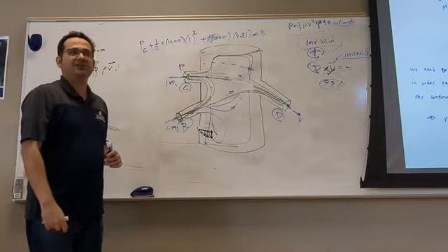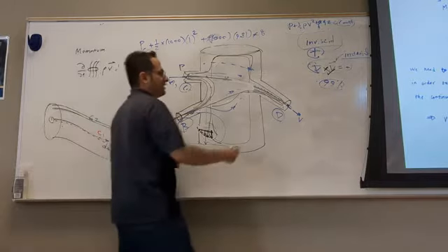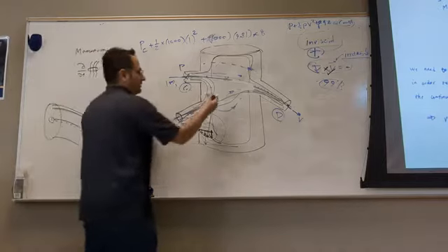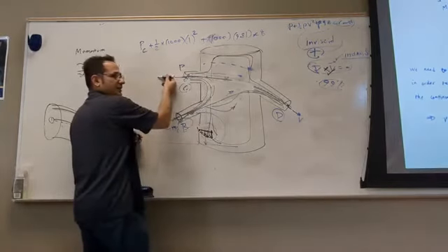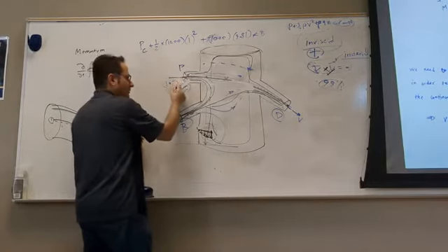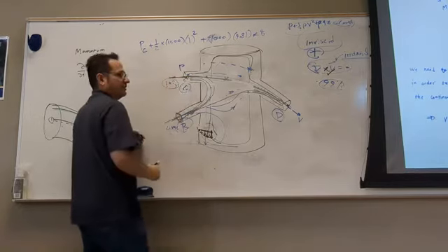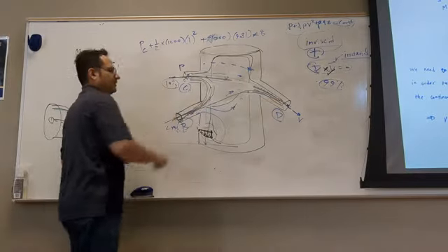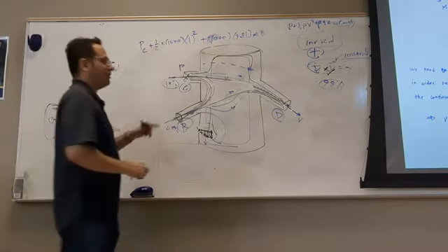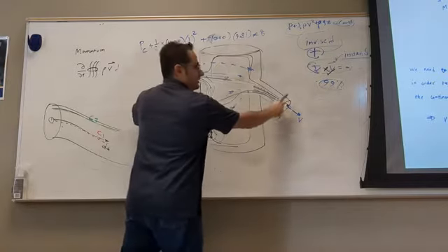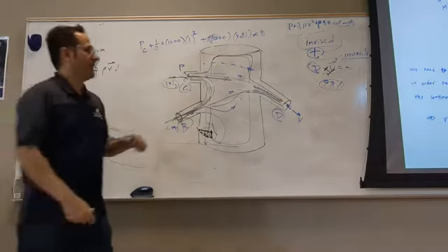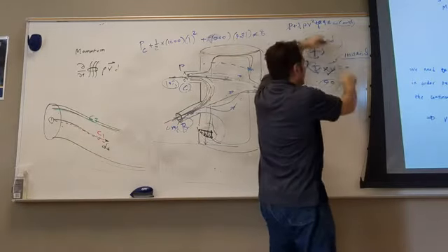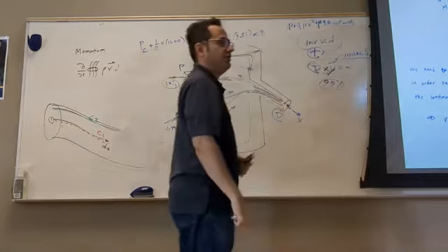Why can't I? Say that again. If I don't make the assumption, let's say the pressure is negative, right? What does it mean? That means the flow is coming here. It's inlet. That means the velocity is the same 1 meter per second, but in the opposite direction, right? That means some part of this inlet is going out, one part of it is going here. Now the question is, can I write the Bernoulli equation between these 2 points? No, not if I have only the implicit assumption. But if I make more assumptions, irrotational, can I do that?